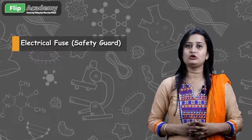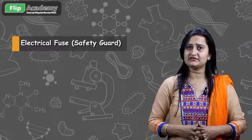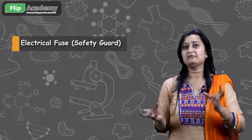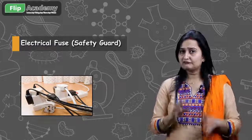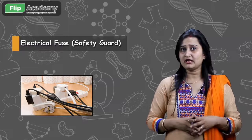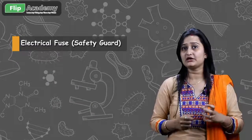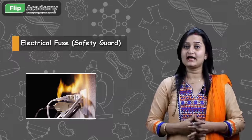Now, next is overloading. What happens in overloading? You have seen sometimes that extensions are provided in our home. Or in the case when we have one socket, then in that socket we use extensions, and many appliances or heavy appliances are connected in one socket. If you switch on the power supply in that particular socket, then what happens? Those power appliances draw heavy current from the electrical connection, and because they draw heavy current from the supply, due to this overloading, an electric fire can occur.